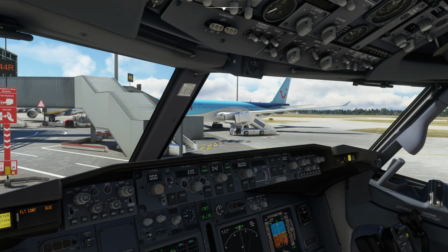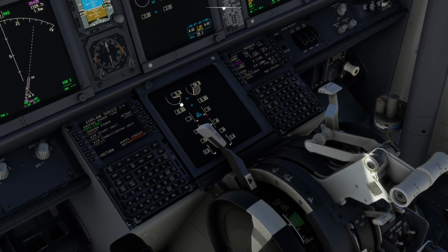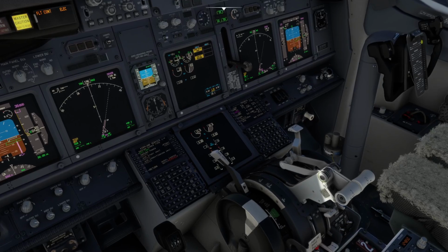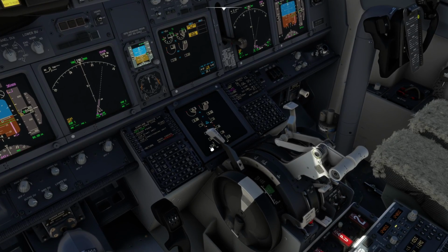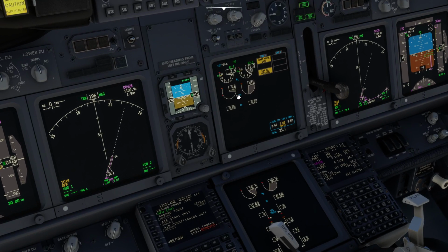Okay, then we can go switch for the left engine over to GRD. We'll use the left ignition system. So you can see the N2 number is coming up. That's the gas turbine being pushed around by the compressed air. When it gets to 20%, we can advance the starter lever for engine number 1. Exhaust gas temperature comes up. Fuel flow is increasing.